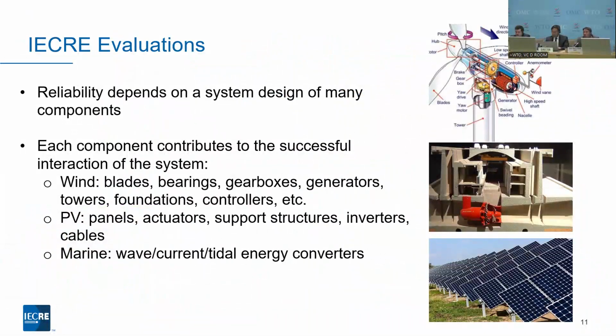So with the 20-year reliability, each component really needs to be examined in detail. In the wind turbine industry, we look at blades, bearings, gearboxes, generators, the towers, the foundations, and the controllers, and these have to be looked at in great detail and the designs evaluated to meet the 20-year requirement of the standard.